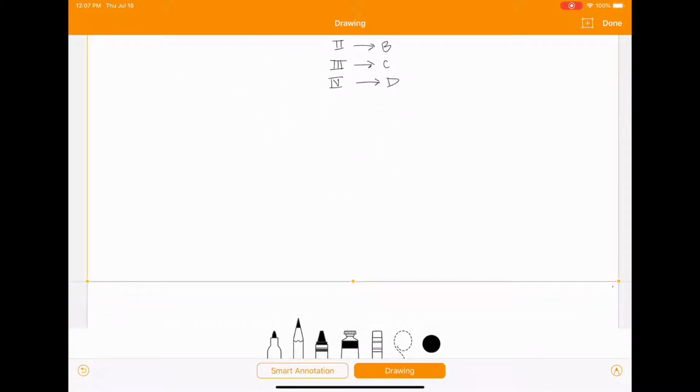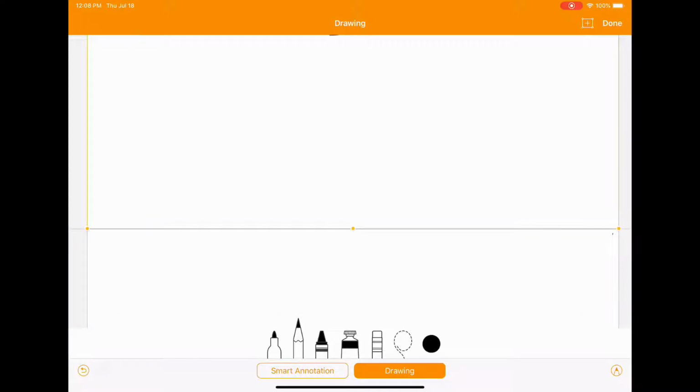So once you pull off your basic wind speed from one of those graphs, you can go ahead and find your velocity pressure at different heights along the height of your building. And this is given to you by using equation 26.10-1.